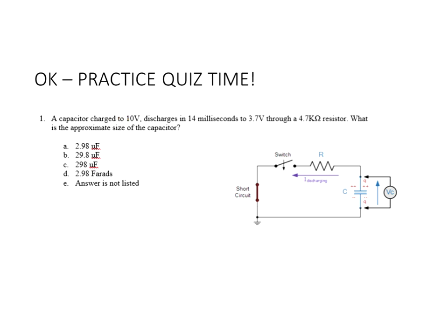And 37% is how many time constants? 1. So I have one time constant, tau, is equal to RC. And it says how long does it take? 14 milliseconds. So 14 milliseconds is equal to R times C. But what is given? R is 4.7K. So 4,700 times C. Now how do I solve that? 14 milliseconds divided by 4,700. Do it on your calculator.